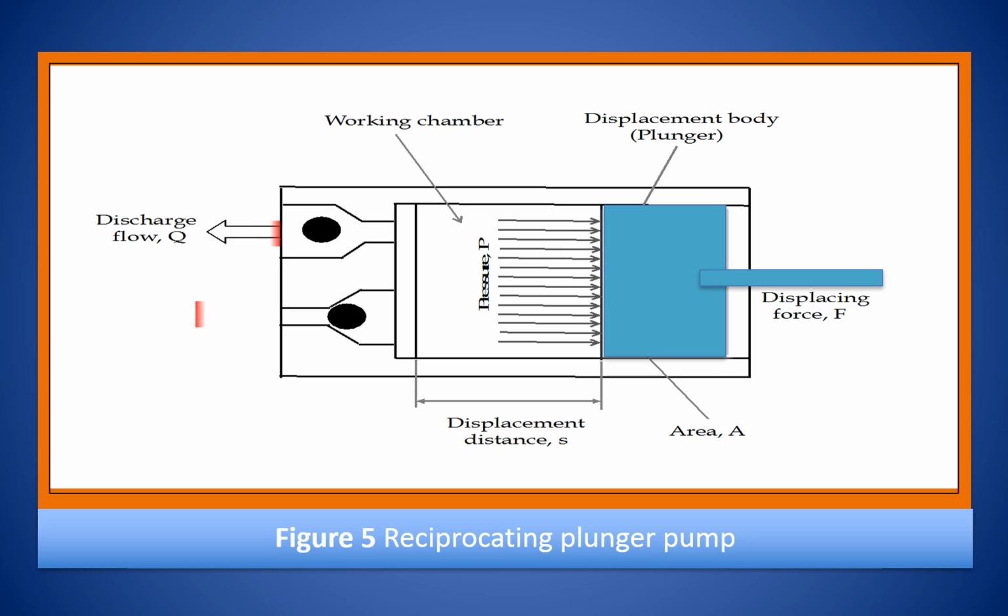This shows a simple schematic diagram of a piston pump with increasing and decreasing cavity during the suction and discharge stroke respectively. The liquid flows to the pump as the cavity on the suction side expands, and the liquid flows out of the discharge as the cavity collapses by the action of a forward and backward moving piston or plunger.